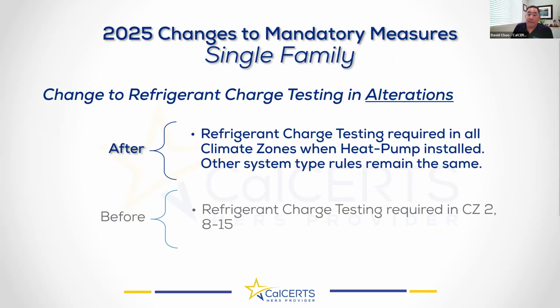Okay, so this is great. The CEC is proposing to change when refrigerant charge testing happens in mechanical changeouts, or alterations. A lot of people go into existing houses and change out the air conditioner. Previously, it was only required in climate zones 2, 8 through 15. Now, when a heat pump is installed, refrigerant charge testing is going to be required in all climate zones. So this is specific to heat pumps, right?